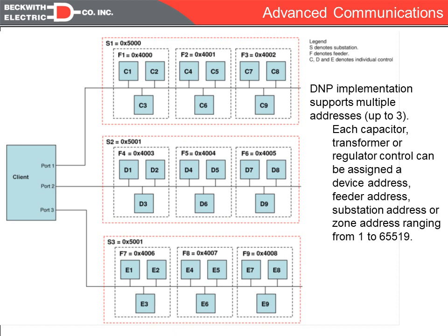So this gives us 2 advantages. If we have every single control in the system have the same station address, then with one single command we're updating all the heartbeats simultaneously, which is going to reduce the bandwidth requirements greatly, but it's also going to synchronize so that they all come in and out of heartbeat at the same time across the entire system.